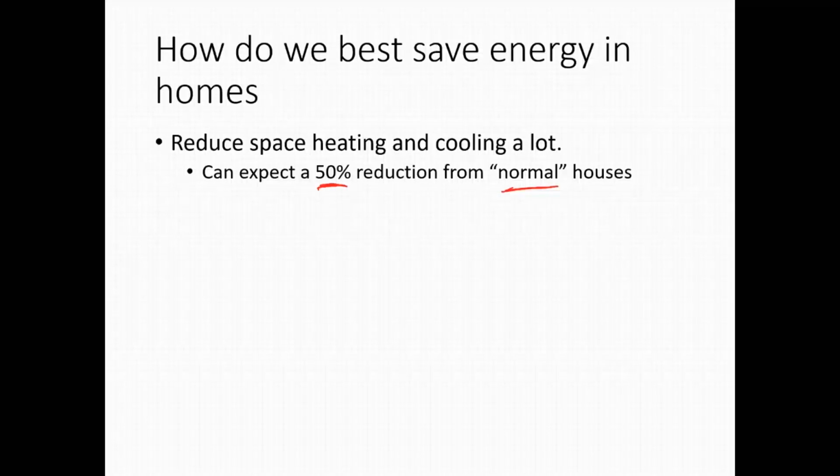We have to consider R values in our assemblies, our wall, roof, floor, etc. Our window metrics, what kind of windows we're putting in our house, our building orientation in relation to the sun, and trying to utilize some of that free heating that the sun's radiant energy can give us. We have to think about the types of systems that we're specifying in our homes. And when we're working to reduce energy use and making alterations to all of these things, we have to remember the building as a system again, and think about moisture and fire risks, right? There are fire risks associated with all of these changes that we're making.